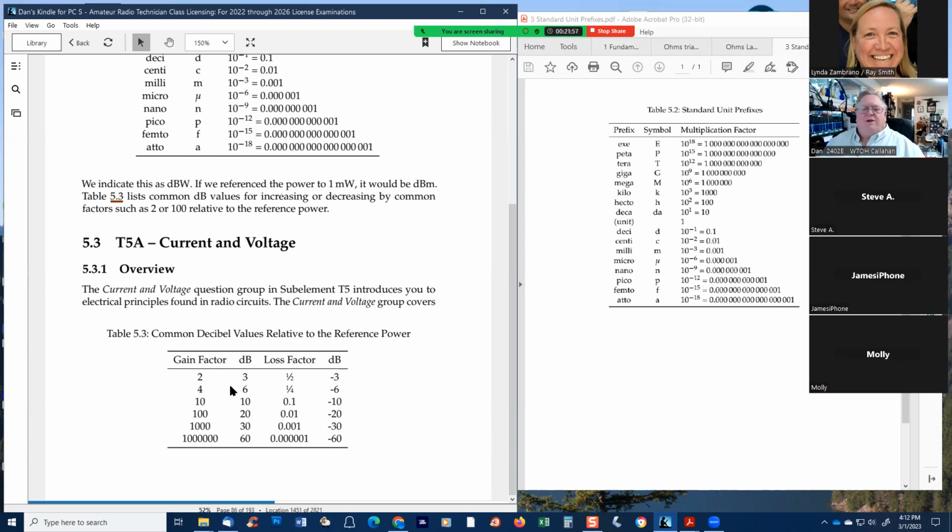So if you double it again to 6 decibels, now it's 2 times that, now it's 4. And then you notice they say 10 decibels is a factor of 10, 20 is 100, 30 is 1,000. So you see it increases rapidly. But for you to remember, 3 decibels doubles it. That covers a lot of what you really need to know. Make sense? Bueller? Okay.